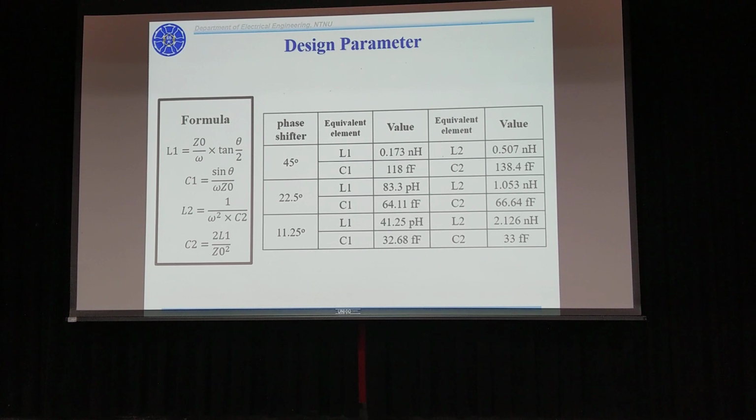When designing switching T-type phase shift bits, we can calculate the ideal capacitance and inductance according to the equivalent circuit. After getting the ideal capacitance and inductance, we can analyze the equivalent capacitance to decide the size of the MOS.